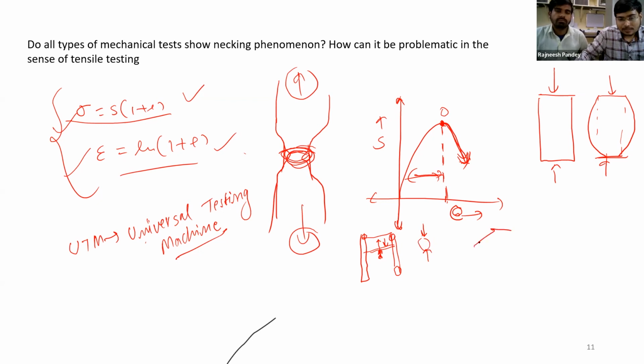Now, suppose you have a specimen and you create a die like this, with a hole throughout the die, and you place a sample here, and there is another die. So the specimen is throughout these two dies, and if you press this one and pull this one, you would put a shear stress on this specimen. So a shear test can also be done.